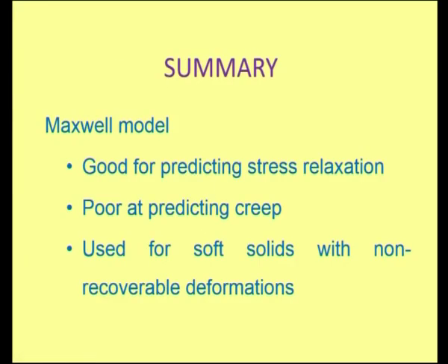Further, in the Maxwell model, earlier I had told you the Maxwell model, and then the Kelvin-Voigt model, which we will discuss in the next episode, has some inherent drawbacks. The Maxwell model is very well suited for performing the stress relaxation experiment, whereas it is poor in predicting the creep properties. That is, if you subject it to constant stress, then the material fails to explain the viscoelastic behavior. So, this Maxwell model is generally suited for soft solids with non-recoverable deformations.